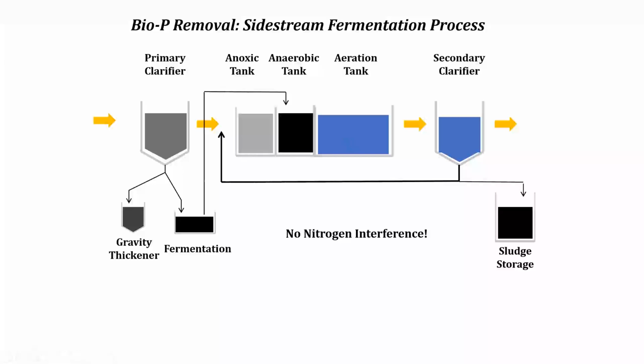is very low. Those plants, those three I mentioned, Missoula, Bozeman, and Kalispell, they all produce an effluent total phosphorus of around 0.3. I think they do have filtration after the clarifier. I think in all three cases, at least, I know at least one of them does. So it's a very effective design strategy, and it takes a lot of process control and a lot of monitoring conditions past the aeration tank to make sure that solids are not settling out and re-releasing. But really great control, typical, consistently low effluent phosphorus.